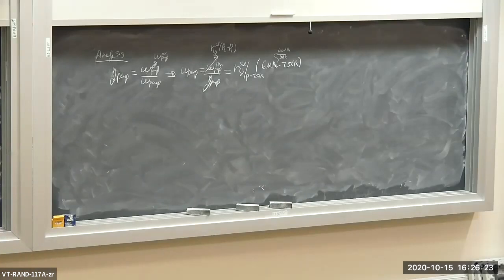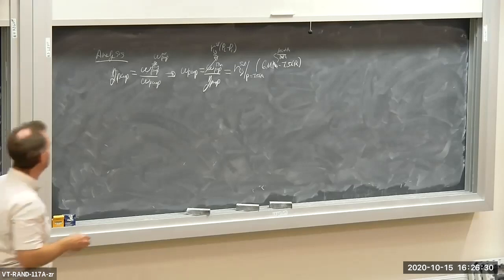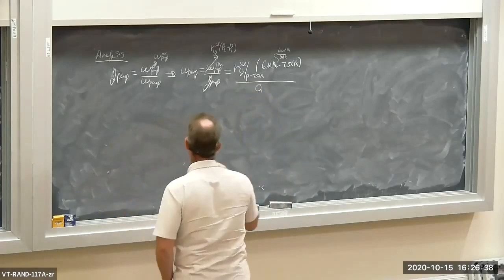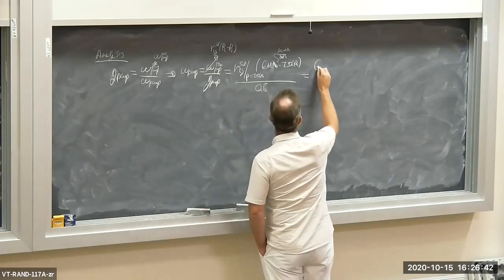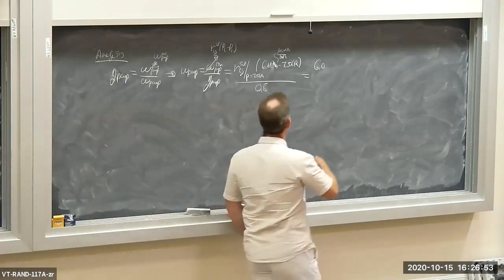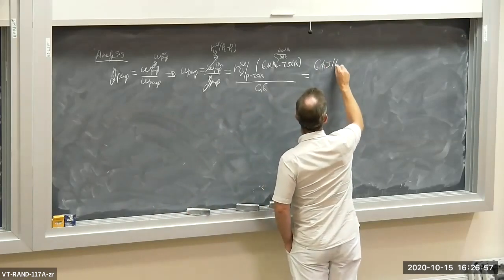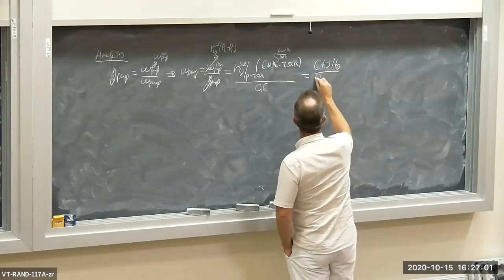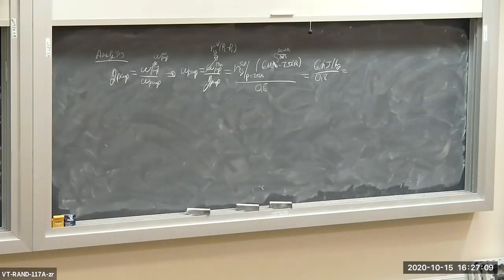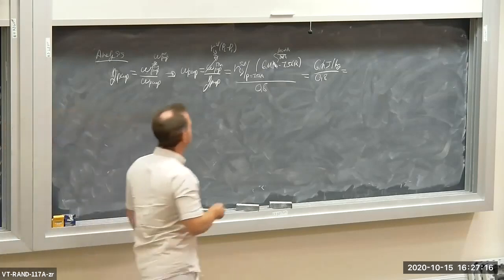All right, we crank through and we find that the isentropic work is 6.04. I'm sorry, what's the isentropic efficiency of the pump? 80%, so 0.8. Let me check this one more time. Isentropic pump work was 6.04 or 6 kilojoules per kilogram. And dividing by 0.8, I get 7.55 or 7.6 if you like.